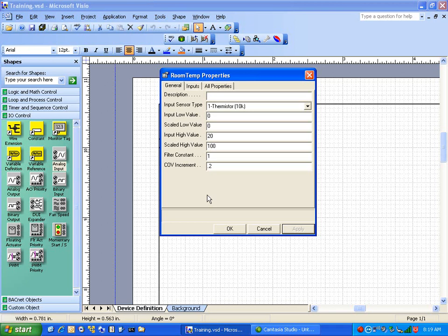And because of trending, because of the way we do our jobs, we really exceed the limits of the BACnet networks in our world. Not really the number of devices, but how many polled points we have. I think if you call Schneider, they'll say they want a maximum of 250 polled BACnet objects.